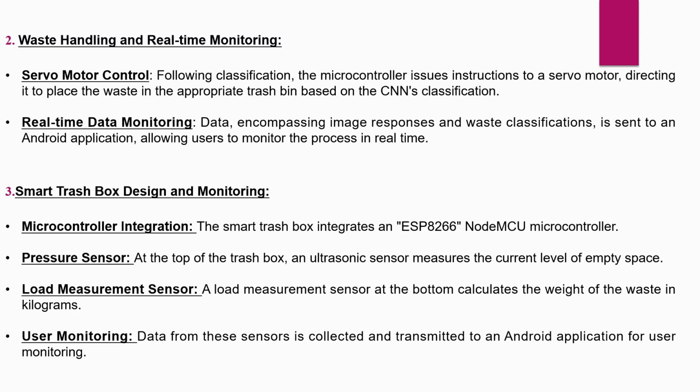Next, the smart trash box design as well as the monitoring. As you know, the trash box is going to be integrated with a microcontroller, especially the ESP8266. At the top of the trash box, we are going to place the ultrasonic sensor. It is going to measure the level of the waste. The load measurement sensor is going to calculate the weight of the waste. Next, user monitoring is done.